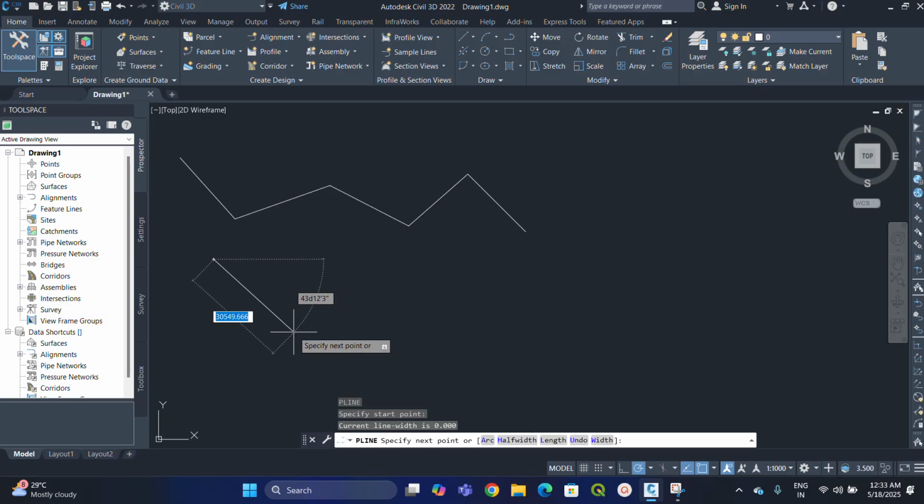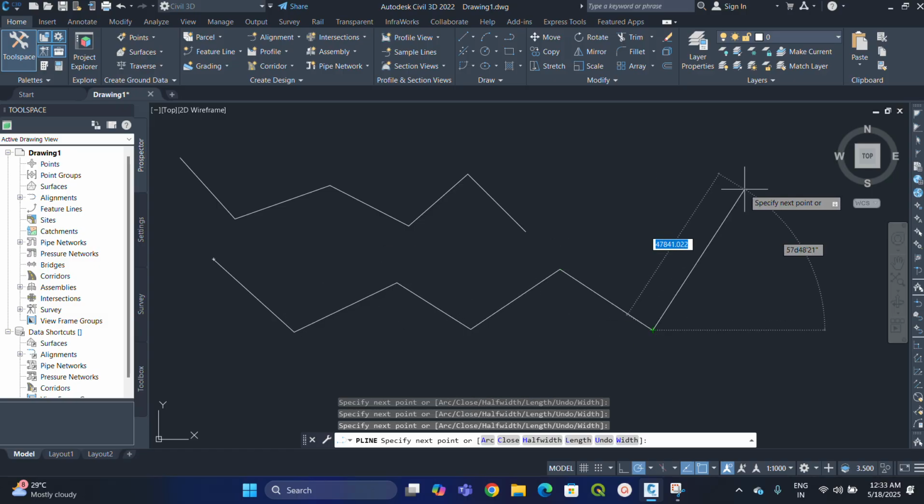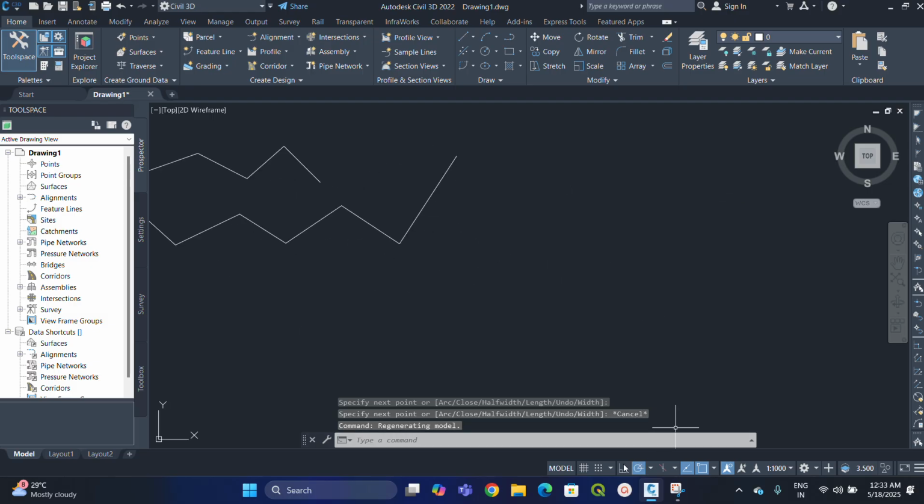So this is polyline. Basically, lines and polylines look entirely alike. This is the snap which we have discussed. Then we'll be discussing this ortho. Ortho is function F8. Once you have clicked ortho mode, it will make you draw the lines in a perpendicular direction only. It will not allow you to draw in other oblique manners.